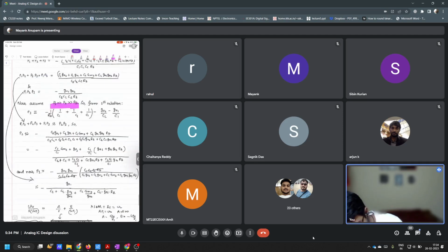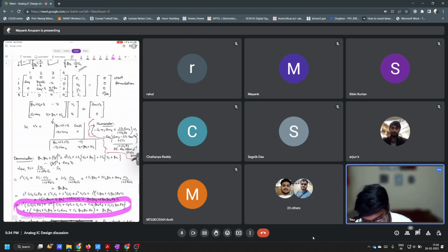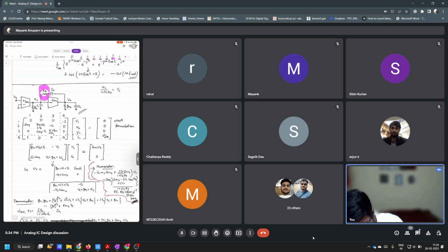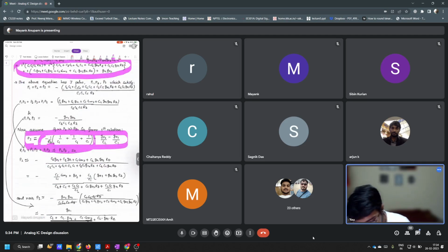When you make that assumption, you start getting these pole locations. You see pole P3, it is like this. This was also explained in the lecture, right? One pole is due to the resistor RZ. You have this RZ here and 3 capacitors CC, C1 and CL in series, and because of these 3 capacitors and RZ, you get a pole P3 approximately.